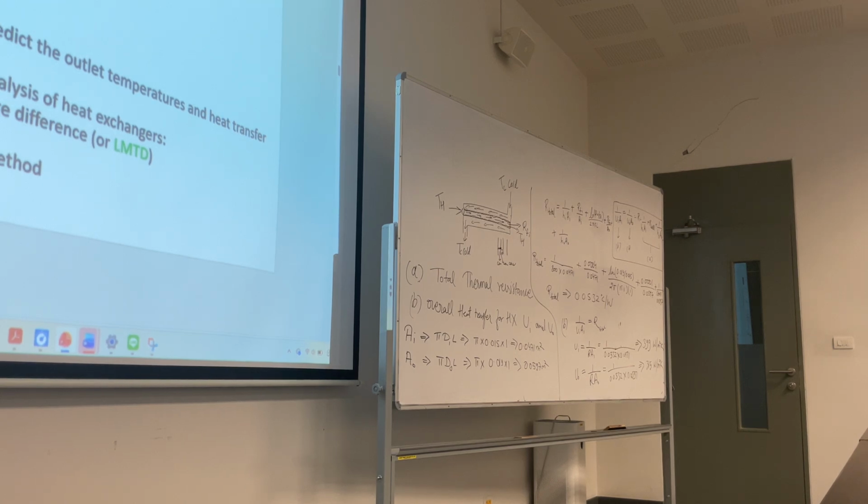know the outlet temperature? Okay, so there are actually two methods used in the analysis of heat exchanger. One is LMTD. LMTD means log mean temperature difference. Second is effectiveness NTU. Two things. LMTD you use when the mass flow rate either is given or you can calculate. Okay, and you need to select a heat exchanger. Select means you need to understand the length of the heat exchanger, right?